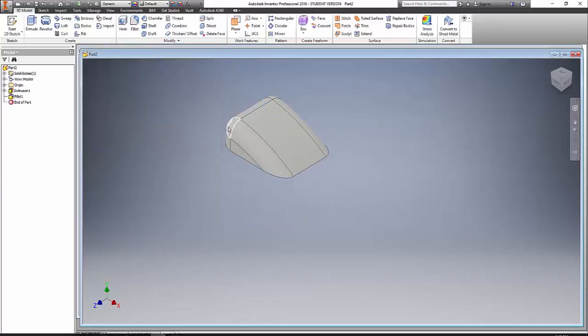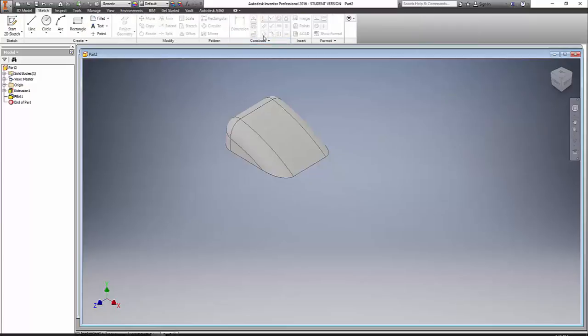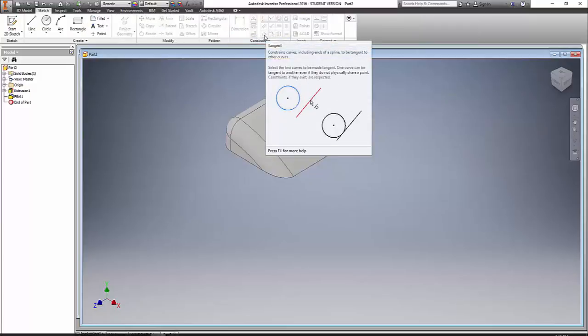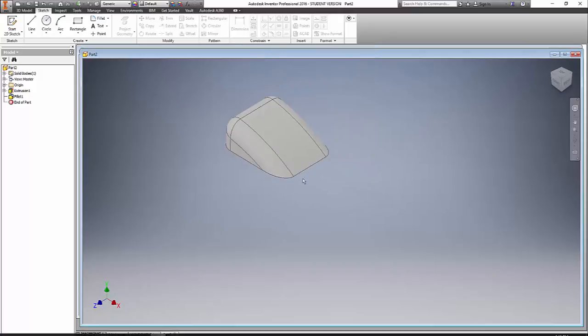Now, if you start clicking on this and it's only doing 1 or it's not showing up, what may have happened is you had a line that was disconnected. That's a possibility. So you want to make sure all your lines are connected and that you apply those tangent constraints right here. If you don't do that, or if you have too many, it may not work. So you may check that as well. So that's our shell. So that's our part 1 of creating our windshield.